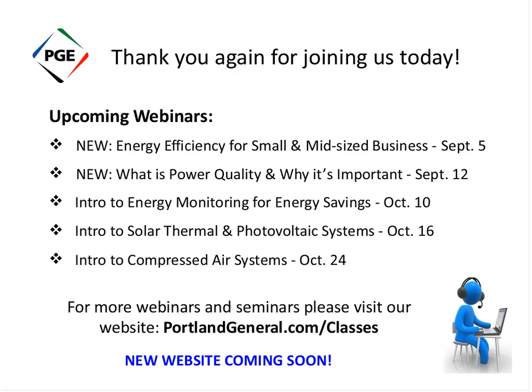So even though the standard T12s aren't going to be available, there was an exception. There's a loophole, so to speak, on the T12s. No surprise there, I guess. But if you have a T12 that has a color rendering of 87 or higher, which is higher than most standard T12s, you can go ahead and use that lamp. So you're not going to save any energy. You will get better color rendering, but you're going to be paying more for that lamp.